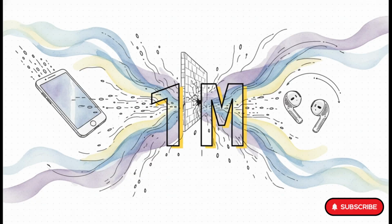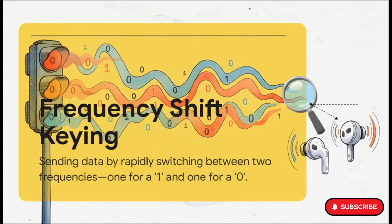So how is it actually sending all those ones and zeros? Well, it uses a really cool technique called frequency shift keying. The easiest way to think about it is like a super fast traffic light for radio waves. It just switches back and forth between 2 slightly different frequencies. One frequency means 1 and the other one means 0. Your earbuds just watch for those super fast changes and read the message.